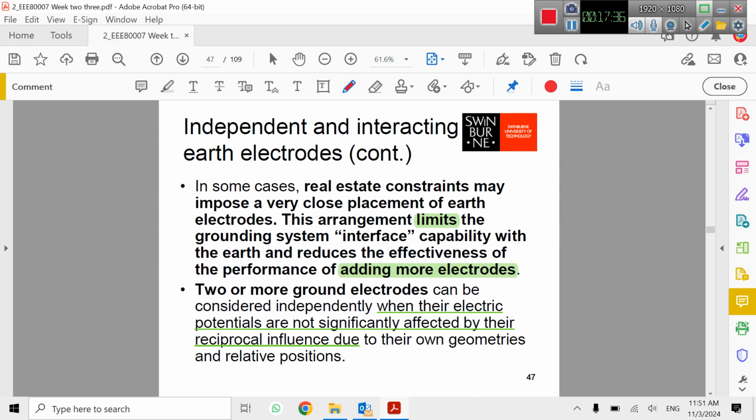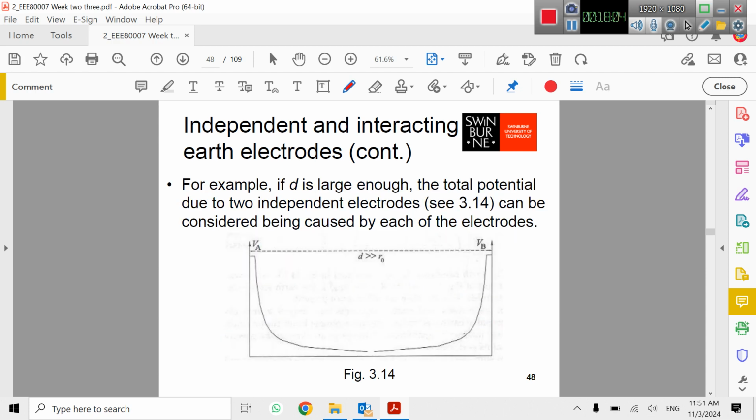So this is very important in some cases. I can remember an example in a substation where the ground resistance had to be significantly reduced for lightning problems and challenges. So we had to install more grounding rods in this case. So we have to consider the meaning of the mutual potential on each rod.